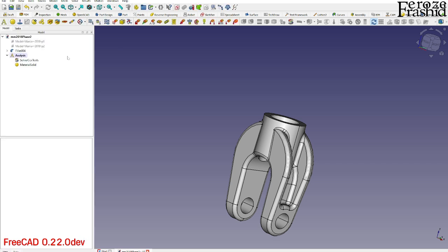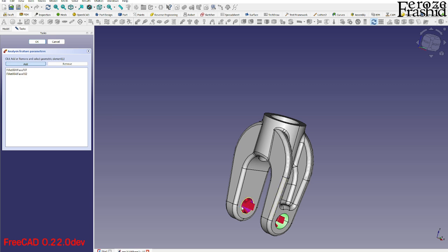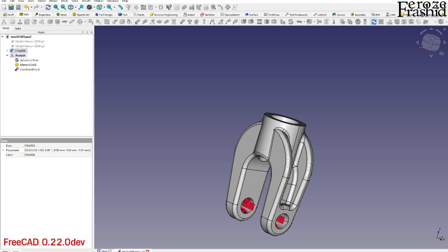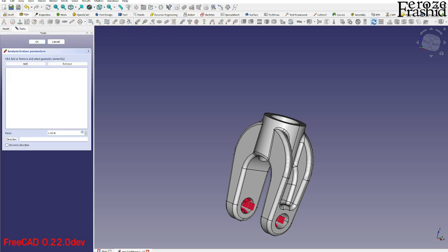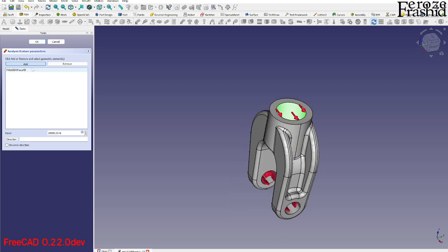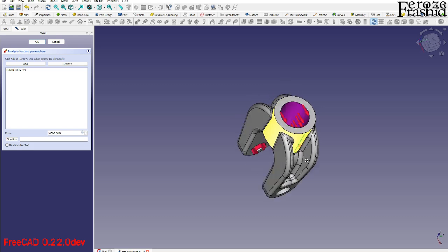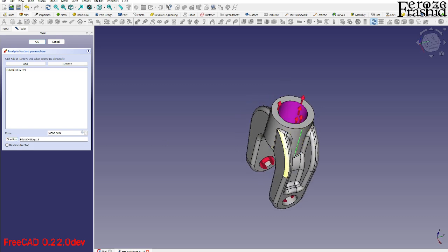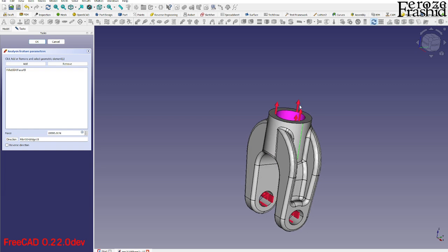Okay. And now I want to go ahead and fix these two surfaces and apply a load of 10,000. And this is just loading surface. We'll have to make it vertical. I think take this add off and select this edge, which is a vertical edge. Looks like it. And hit direction. So that way now it's going upward. If it didn't go upward, or rather it was downward, we can select this reverse direction and that would reverse one way or the other.